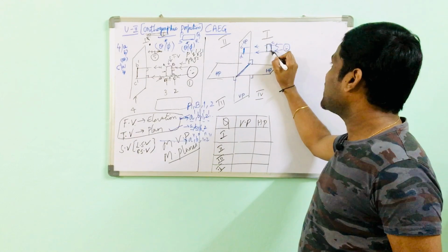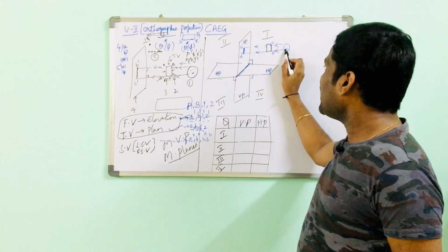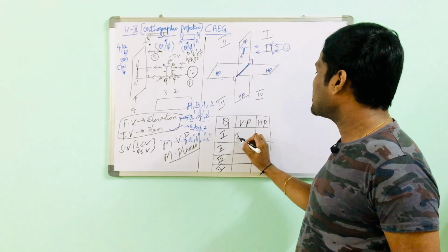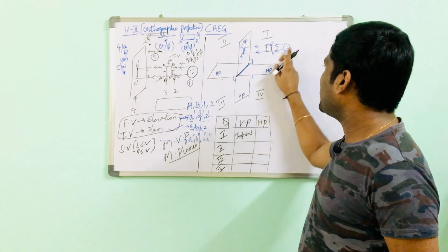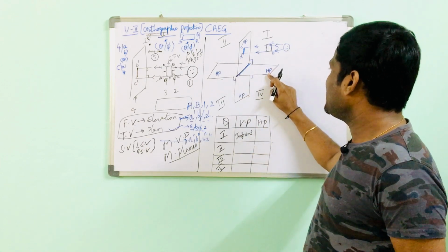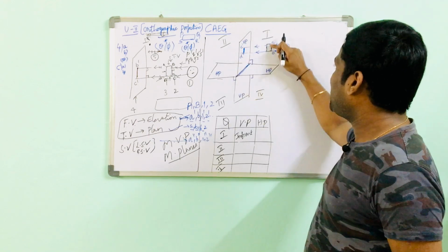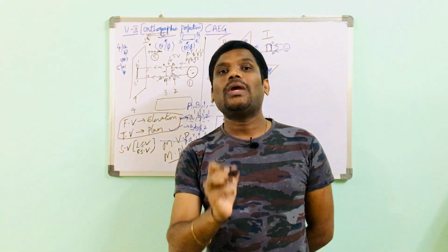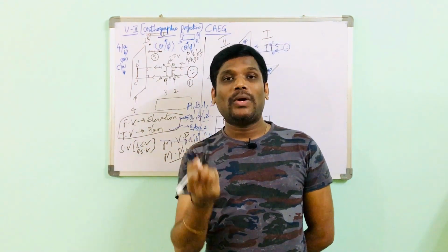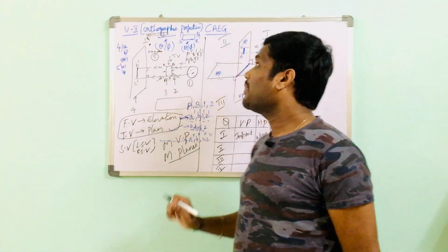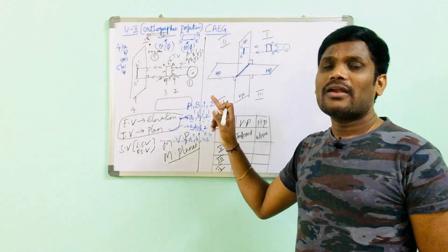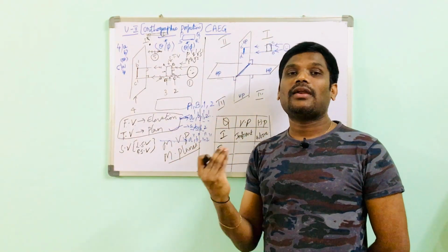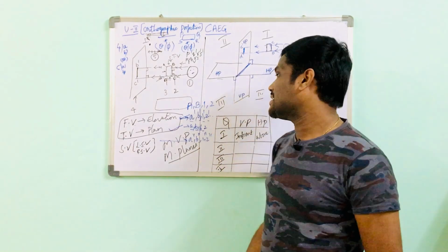Now, in the first quadrant, the object is here. With respect to the vertical plane, the object is in front, dear students, isn't it? In front of the vertical plane. And with respect to the horizontal plane, it is above the horizontal plane. The question which I told you just now: a point A is 20 in front of VP and 40 above HP. Draw the projections of point A. The point is located in the first quadrant. Now, if I go on talking, this lecture becomes too lengthy. Please try to understand and refer to the playlist for detailed understanding, dear students.